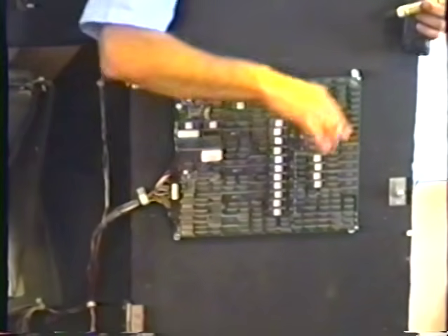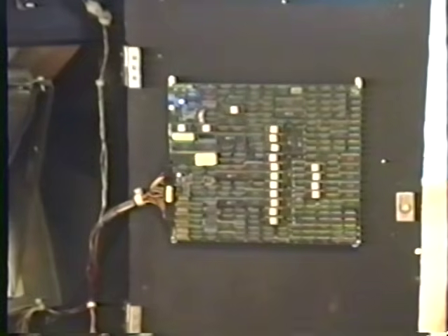But there's another little tool that I always carry with me. It's called a pin extractor tool. It's just a little piece of steel. Real thin. In fact, you can make one out of a thick brass switchblade from a pinball machine. Here's what this is for. Eventually, these pins do go bad. These pins on the connector here, eventually those things will go bad. Especially if you've got a JAMMA game that you've converted 12 times already. And the power pins usually are what goes bad. If you can wiggle this connector and the thing goes on and off, you've got some problems with the pins.